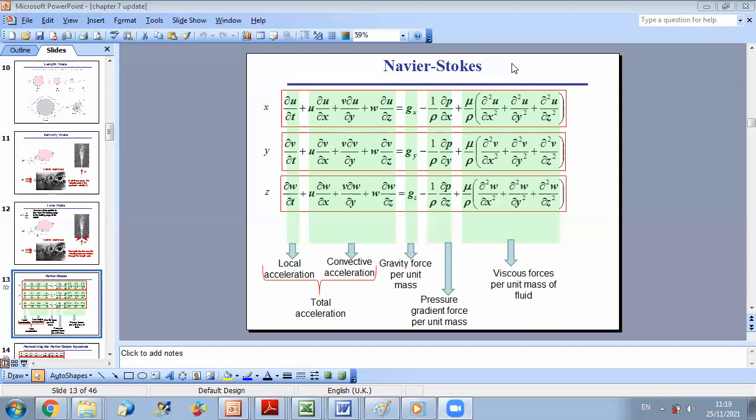Now, to make the experimental results general and to be able to extrapolate them to general cases, we prefer to write all equations in non-dimensional form. This means that all of our terms should be without units. How to do this? For example, in the following relation, you can check for the homogeneity of this equation. All terms have the same unit.